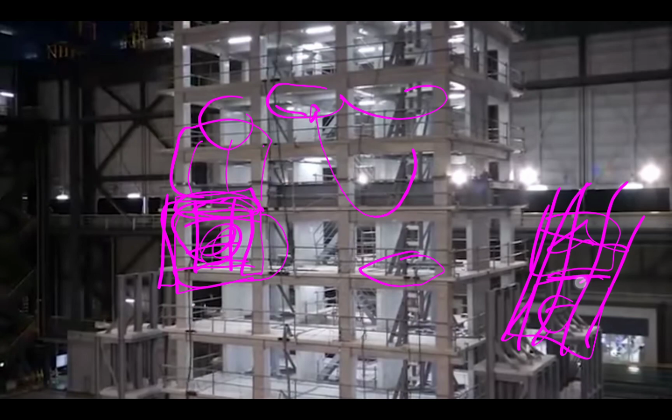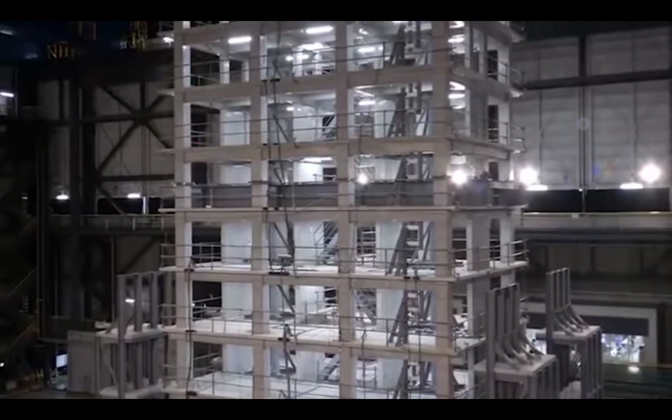Yes, the beam's in there, and you get a little bit of hogging there as it comes back down profile-wise. Here's the beam. But if you get sagging on each side. But that's not a concern here because they didn't put any dead loads on these floors. They just put floors. All right, so yes, they're shaking a floor system, but no weights are on it. No human weight, no dead loads, refrigerators, things like that. Heavy industrial equipment that might be on one of the floors.